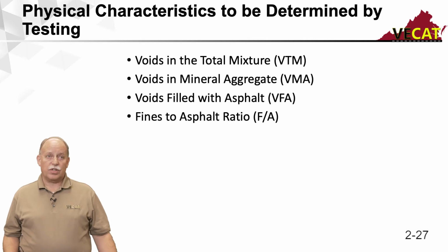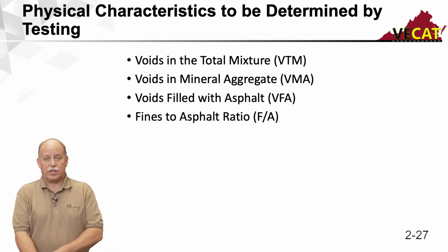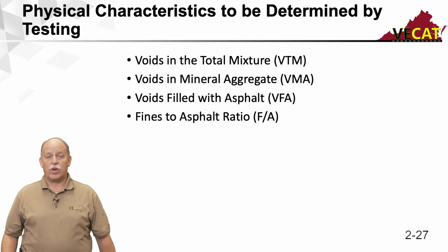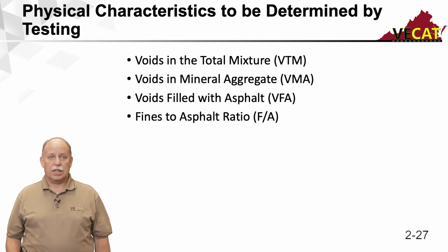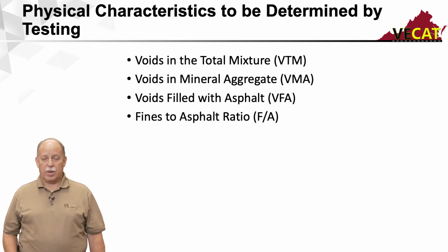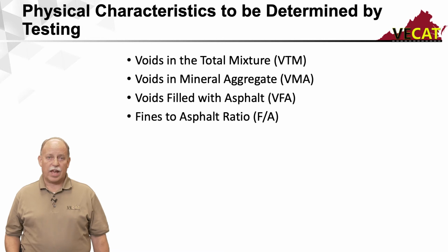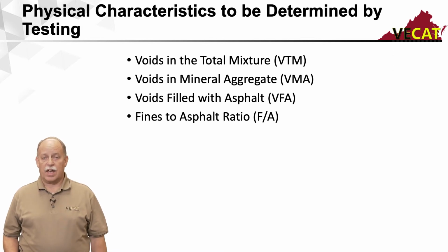So now, some of the physical characteristics that are determined by testing. Things such as voids in the total mixture, VTM, voids in the mineral aggregate, VMA, voids filled with asphalt, which is your VFA, and then we also have fines to asphalt ratio.